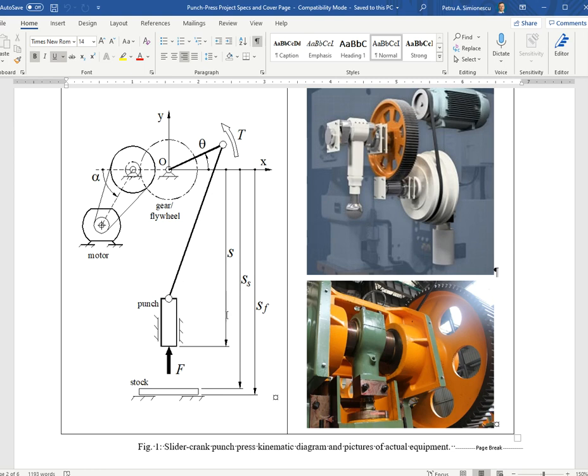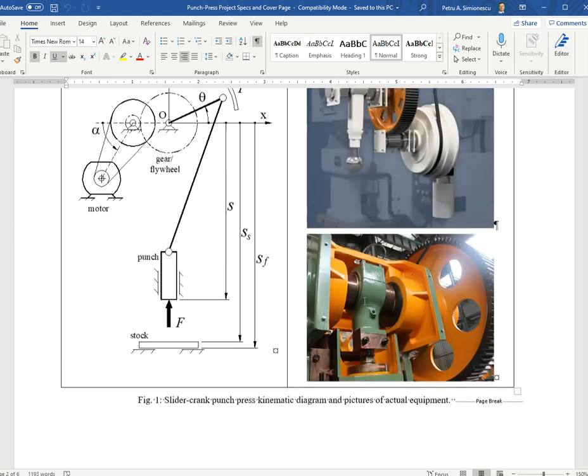In the notes you had a slider crank mechanism. We have a slider crank mechanism that was analyzed, but the punch was moving horizontally. Don't forget, there's an eccentric slider crank mechanism. This appears to be centric, but it's in a positive eccentricity, to the right. So the line of sliding through the center of this pin joint is not the y-axis, not through the ground joint about which the crank rotates.